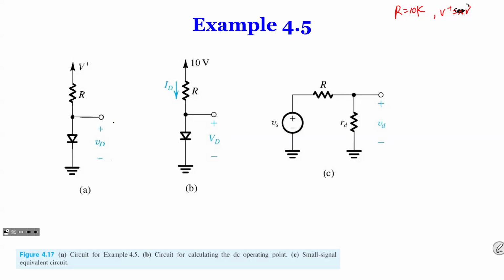So this is where it gets interesting, is that the voltage V plus is 10 volts plus a 60 hertz, 1 volt peak amplitude sinusoid. So it's like plus minus 1 volt sinusoidal omega t. And it asks you to calculate both the DC voltage of the diode and the amplitude of the sine wave signal appearing across it.